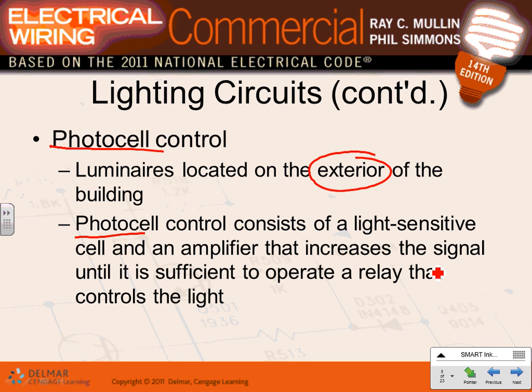So how do you wire that? You come over here. You put an inline photocell here. I'm just going to summarize it a little bit. Contact here. So here's my photocell. Here's my contact here. And then there's a little relay here. And there's a lot of electronics here controlling this relay. And then from here, you go to all your parking lot lights, right?